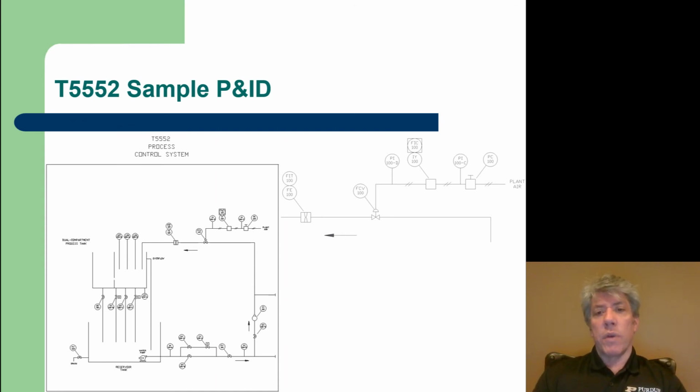So this is a flow indicating transmitter, and what they haven't shown here is how this is electrically connected back, most likely to the flow indicating controller. So there's some electrical system or electrical lines missing here in this.